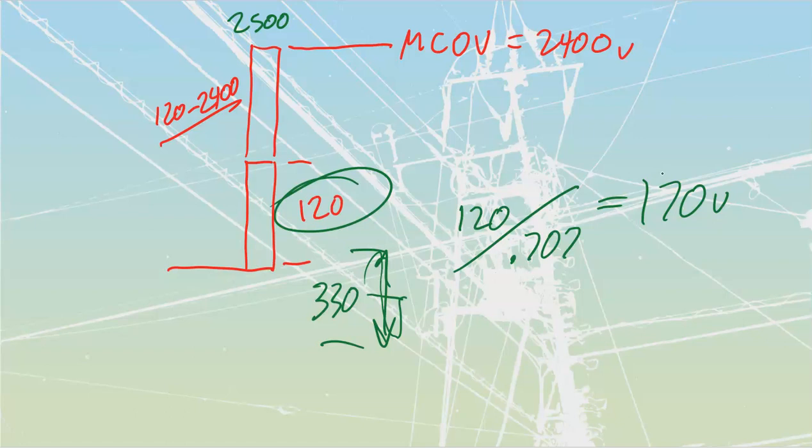Surge current rating is going to be rated in kiloamps, and with a surge current rating it's just going to be how many times I can surge through this thing. What we get is the total amount of current, and we've talked about transformer fault current. Part of what we get in here is not so much that we're looking to deal with transformer faults. It could be, but we're dealing with just large amounts of fault current that's going to go through. 20 kiloamps is just going to be the maximum amount of fault current that it will let through.